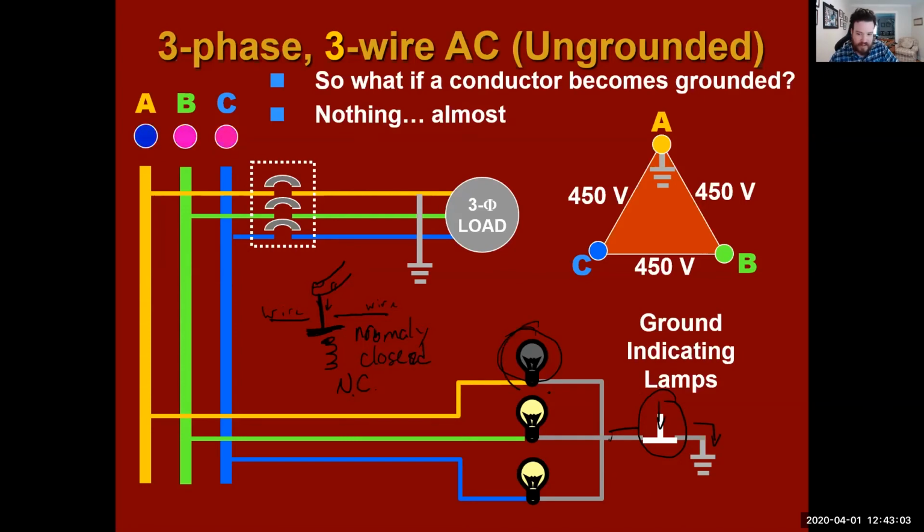So if you're in this scenario right now, what's going on? Like I said, this ground right here might as well be connected as a wire. So instead of having two sides here of voltage being fed on the same phase, what is going to happen as soon as you push down on this button? You only have one side. Exactly. So what happens after you only have one side on this specific light bulb? Well, actually all three. What would happen? They all go back on? They would all go back on.